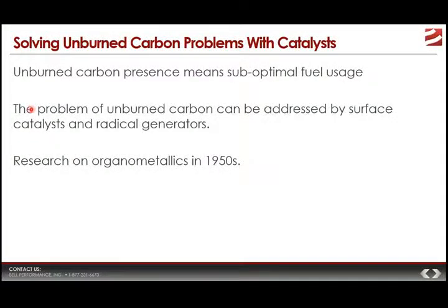Now, unburned carbon, or partially burned carbon, the presence of that after combustion is a sure sign that the combustion process has not been completed to the optimal level that the engine was designed for. So if you've got soot coming out in the emissions, or if you're seeing carbonization of certain areas in the combustion or post-combustion zone, what that tells you automatically is that carbon should have been burned. That should not be there. And that means that you're not getting full combustion and something is causing that.